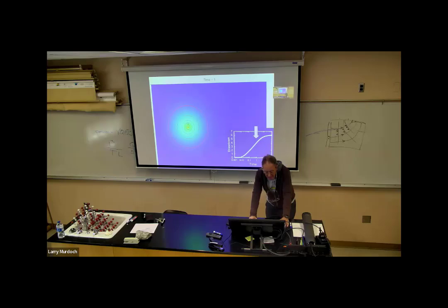All right, well, that's about to change because no aquifers are of infinite extent. There's always some boundary. And in this case, we have a boundary over on the left side that's a stream. And we're assuming that stream is cutting through the aquifer, and so the stream is causing the head in the aquifer to be equal to the head of the stream. So it's a constant head boundary. So here's what happens in the next leg of time.